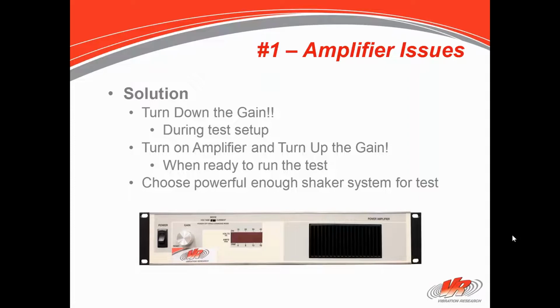Well, it's very objectionable. So the solution is to get the best situation out of the pieces that you have: turn the gain of the piano all the way up and just use enough gain on the amplifier to get the volume required. That will give you the best signal to noise ratio for the system. And you kind of have the same situation with a power amplifier. They're made to be big and powerful, and perhaps the gain is going to introduce more noise in the background if it's cranked up higher.